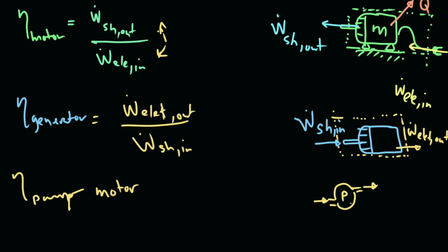So there's actually a shaft. In order to power the pump, we rely on a motor, typically. And that's the motor that I just drew up there in green. I'll just put an M here. And that is powered by an electric cord, typically. And so the efficiency of this combo of these two components is equal to the efficiency of the pump, I'm just going to put eta P, times the efficiency of the motor.